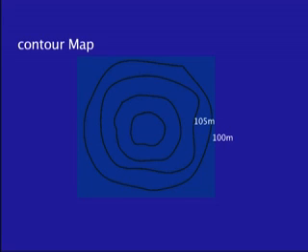So, in other words, once you have these M circles or a number of them drawn on a chart or on the complex plane, on that you can draw the polar plot, and then for almost every point on the polar plot you can read off the value of the gain. Let me illustrate this with the help of the contour map. Now, here is the contour map of a terrain, and let us say somebody starts moving and the path of that person is something like this. Let us say the person is going in the direction indicated by the arrow.